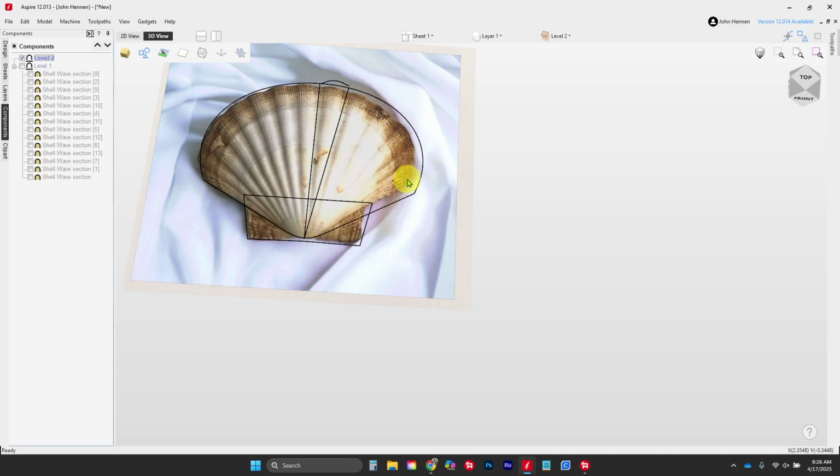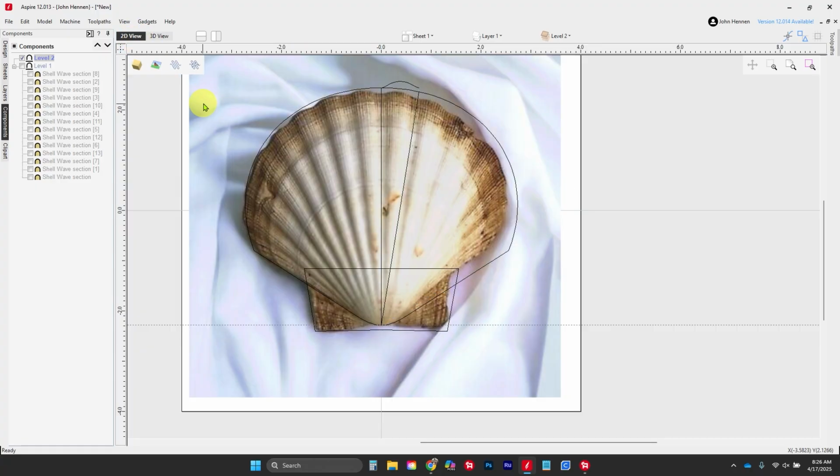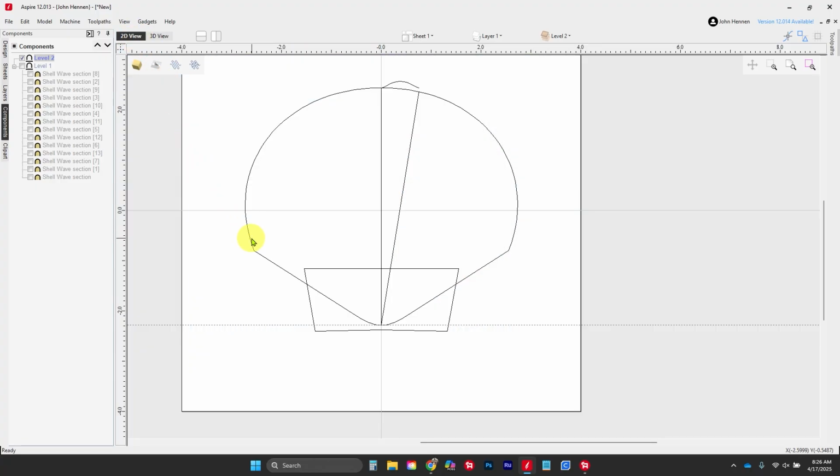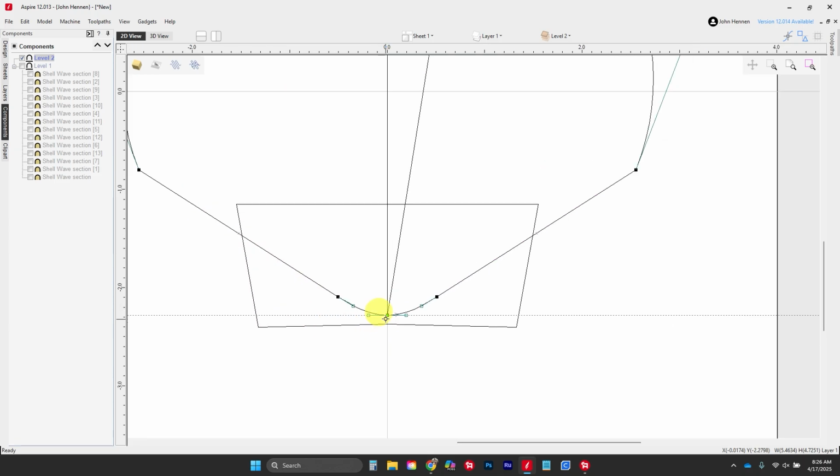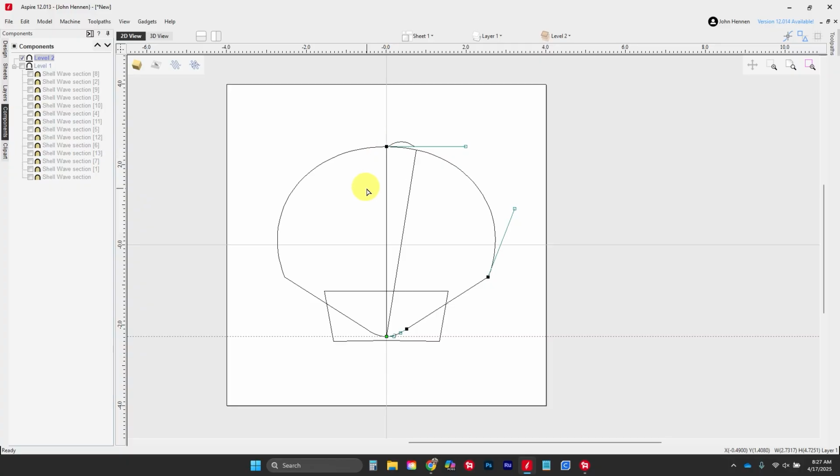So to build this as a 2-rail sweep, it's just slightly more tricky in how we want to do it. So we want to start tall and then go small. So let's think about how we're going to build this thing, see if we can make it happen. First thing we're going to do is grab this guy here, go to our node mode, and we're just going to cut it back apart. So we're going to cut that there, and come to the top and cut that there. Now we have our 2 sections again.